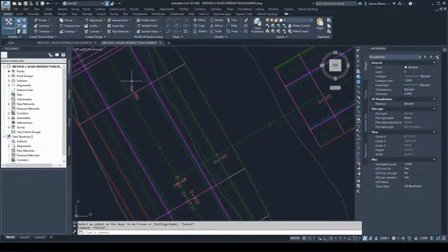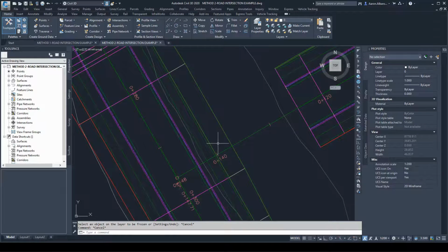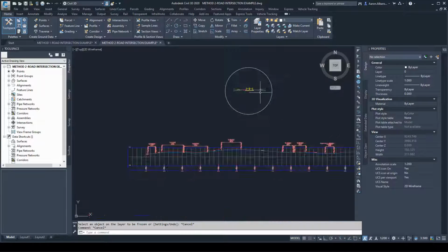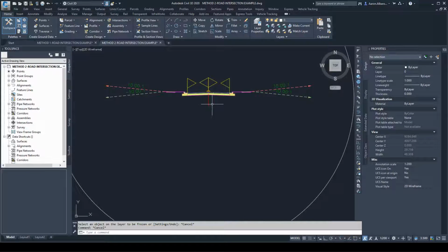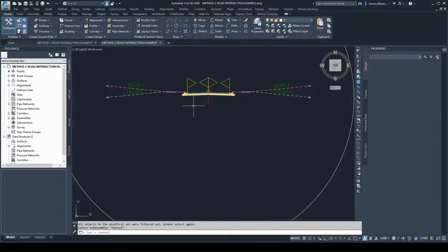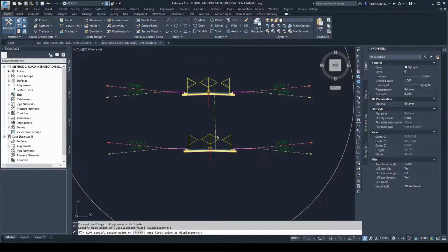If the car is traveling along the alignment this way, when I turn to the left to go to the other road, alignment 2, I shouldn't go over the curb, the sidewalk and the daylight, which are here on the left-hand side of my road. So I have to create a new cross section just for that region that doesn't have these components on the left-hand side. So I'll copy this, just select that and go to Home and copy from there, because I don't want to copy sub-assemblies, the whole assembly.